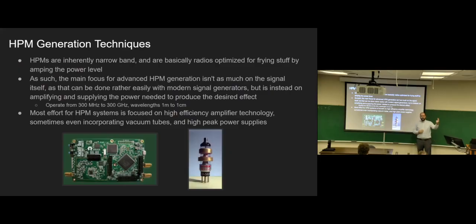With software-defined radios, the signal comes in, is received by the antenna, and is almost immediately sampled with an analog-to-digital converter, turned to bits and sent to a computer instantly. And then when we want to send something out, bring bits out of the computer, put it through a digital-to-analog converter, send it out to the amplifier, boom. It's very flexible. They're cheap. This device is a commercial one. It's very strong. It has a crazy wide band of 1 megahertz to 6 gigahertz, pretty good. And it's about $300 on Amazon. It's a pretty solid price.